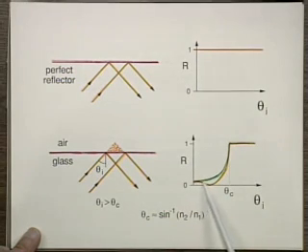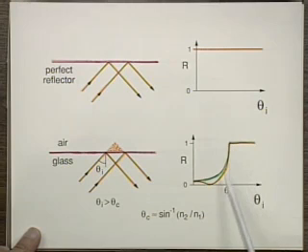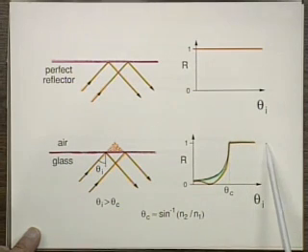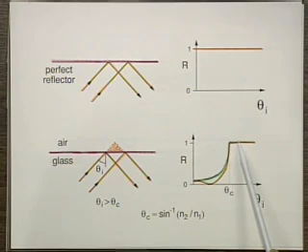And for the other polarization, it doesn't quite go to 0, but again still rises and goes to 100% at the theta critical. So it doesn't matter which polarization, both polarizations will go to 100% for theta critical and beyond. And that's what we take advantage of in fibers. And let me tell you, this is really 100%, because you wouldn't get such low loss fibers if it weren't.